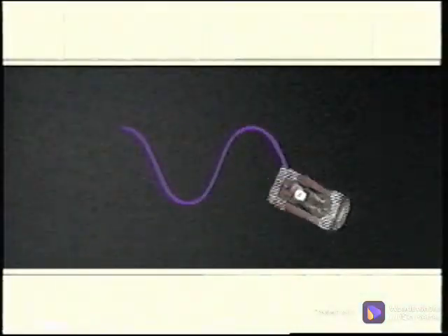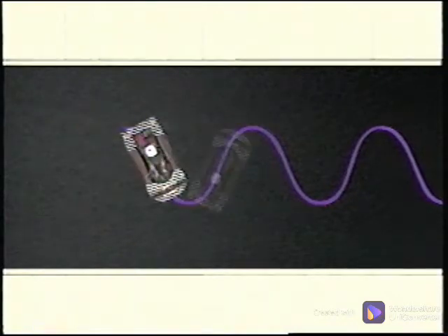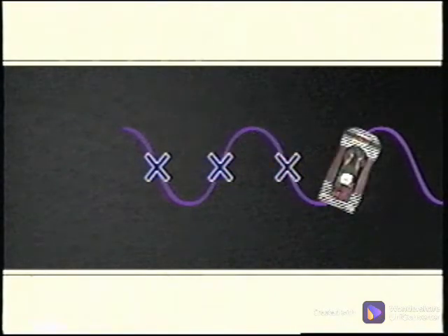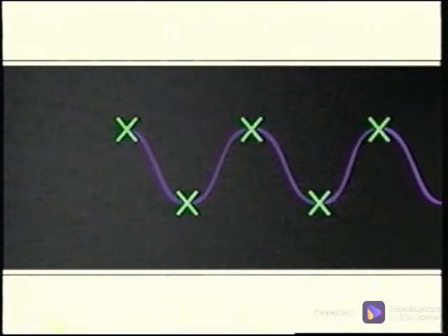In another program, Introduction to Vibration Analysis, we use go-karts to demonstrate that a waveform can show three precise measurements. The displacement measurement is the total distance traveled from one peak to another. The greatest speed or velocity is at the midpoint, and the greatest acceleration is at the turning points of the waveform as the direction changes.